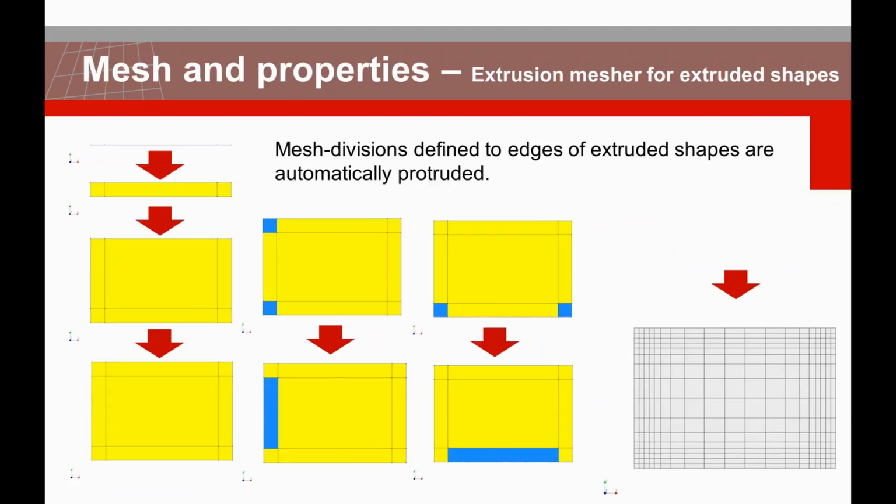Another thing that you need to consider: you can extrude from 1D to 2D. So we have one line, we extrude line to sheet, then we do that the other way around. So now we have one model here, and the last panel, we're going to extrude it here. The advantage of this extrusion is you only need to assign a seed to one of the edges, because, due to the attribute of extrusion, the program automatically recognizes all adjacent edges and reads the corresponding seed from one of the predefined.